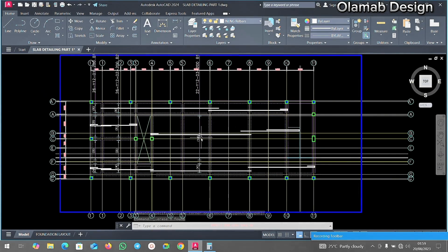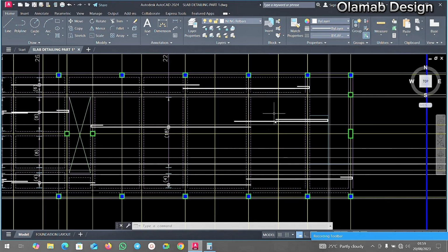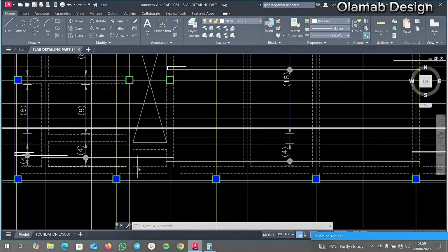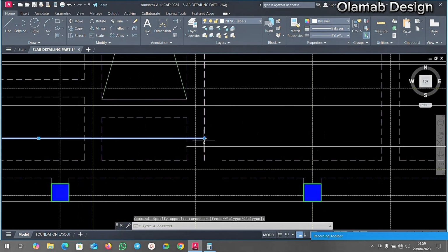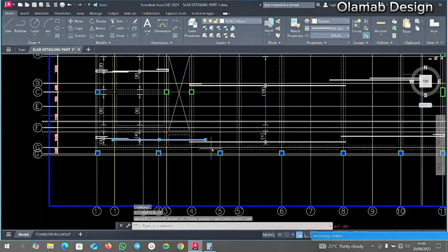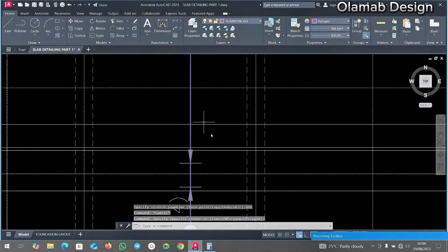Then for this, we are okay with the whole of this panel up to this stage. And the next one is going to be for this particular panel, because this one here has served us to the top of this beam. Mind you, I think we are good to go. Let's extend this reinforcement to lapping by 600. I'll hit enter. Then let's call this out. So let's just copy this.